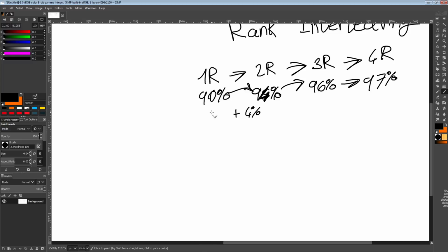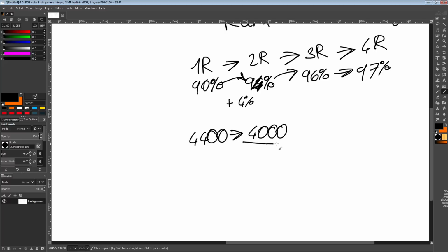You should just search for them. But on Intel platforms, like Z390, with 1 rank you can probably quite happily run 4400, maybe even higher frequencies at decent timings. And if you go from 1 rank to 2 ranks, very quickly you'll find that now you can do like 4,000 megahertz. Well, I mean, mega transfers per second. See, everybody does it. If it's 4,000, it's not 4,000 megahertz, it's 4,000 mega transfers. But anyway, from 4,400 you'll end up going to like 4,000.